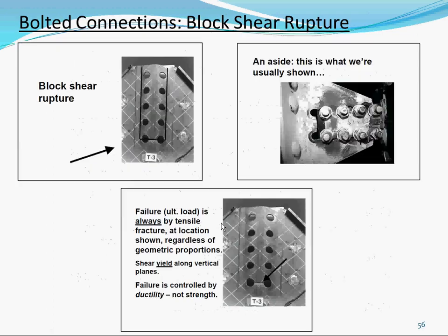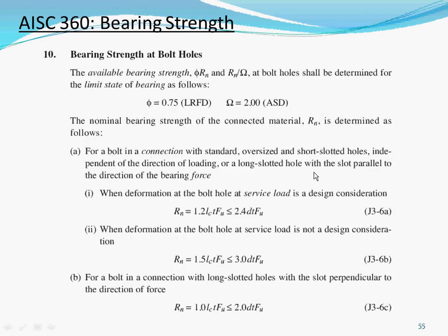So that's why when we're doing the design check, especially for bolted connections, I'll do that as well. This check is where we're doing the bearing of the bolt, as well as the bolt shear tab. We're bearing on one single bolt that we're pulling on.